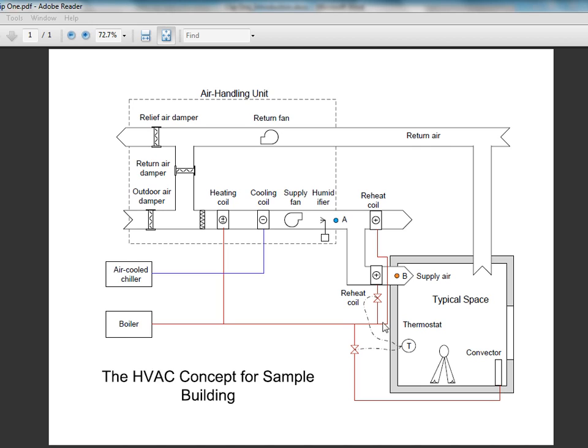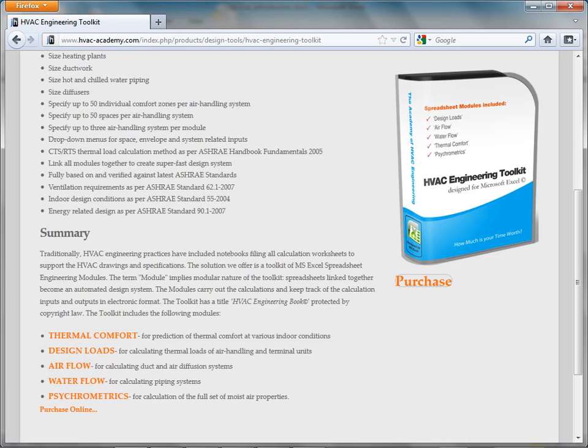The other schedule in the drawing outlines the exterior wall, roof, window and entrance door arrangements. For example, the exterior wall includes 5 layers: a 4-inch brick, an air space, a 1/2-inch fiberboard sheathing, a 3.5-inch batt insulation, and a 1/2-inch gypsum board. This information will be required for the calculation of heat transmission through the exposures.